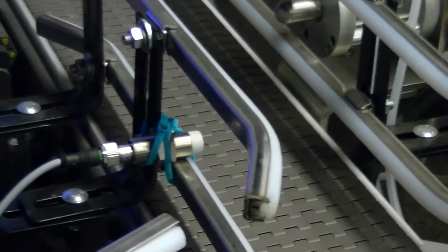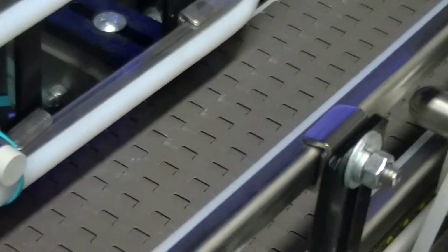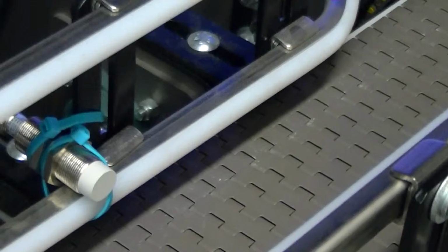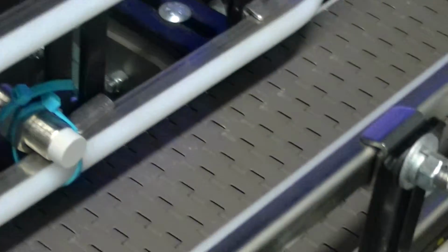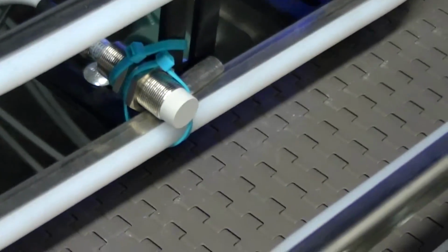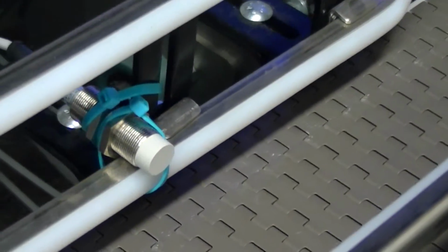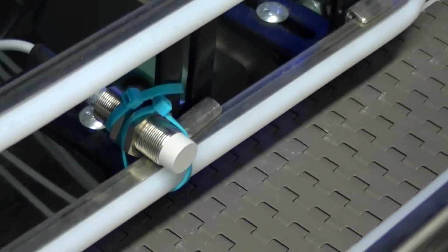Once we hit this proximity sensor here, that will actually trigger this contact. John, do you have something metal so they can watch that light up? If John waves the watch in front of that sensor, it's going to light up that contact and open up the gate, rather. You can see the contacts light up. That sensor puts out some kind of electromagnetic field, something about the flux lines. If a metal object comes through, it'll concentrate the flux lines, so it can detect metal objects like that.